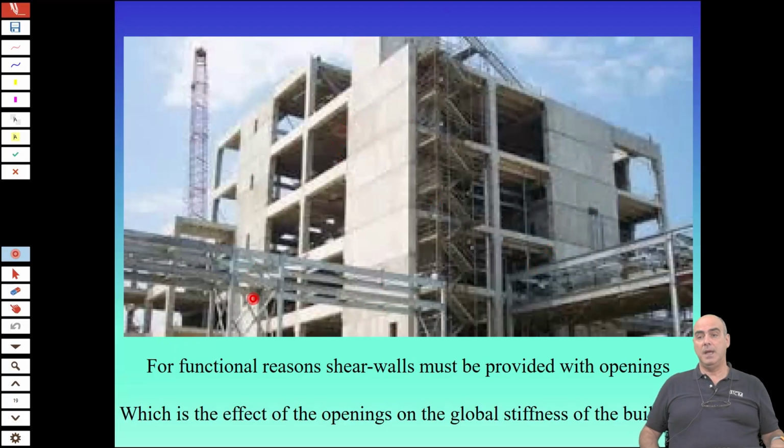Sometimes, as we have said, the lateral load resisting system also incorporates staircase cores. And especially if you are in an apartment building, on the staircase, on the landings, intermediate lengths, you will have some windows. Also, in that same core, you have the entrance doors to the apartments which have to be allowed. So you have openings. And what does this imply?